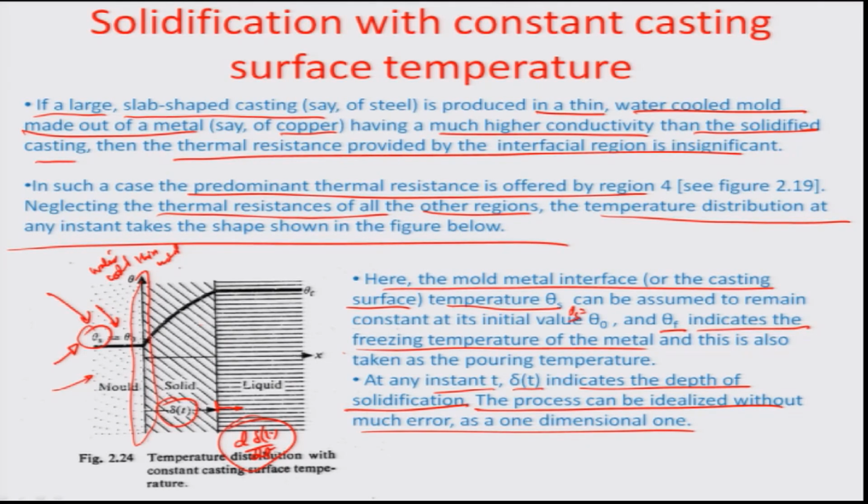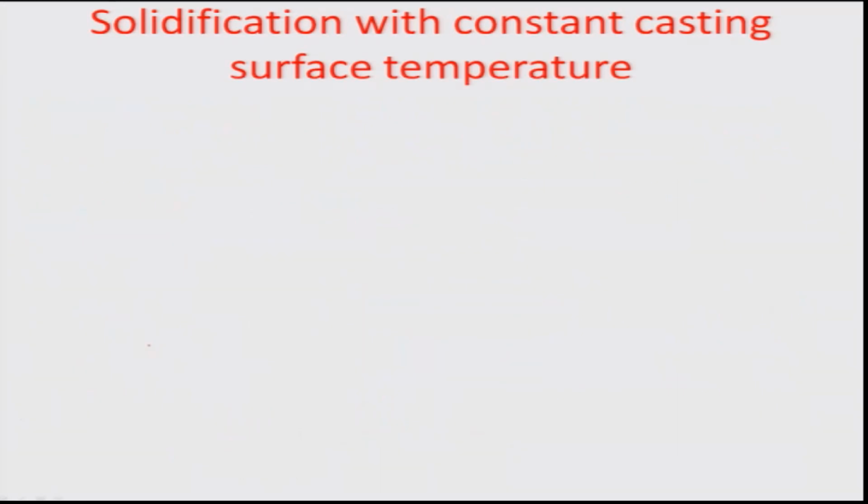The maximum thermal resistance which is offered to this liquid temperature, the freezing temperature, is really the solidified portion of the metal, and the other end of this is really a constant temperature surface or constant casting surface temperature theta s. So let us see in this kind of a problem what really happens, or what would be the estimation of the solidification time. So let us estimate the solidification time